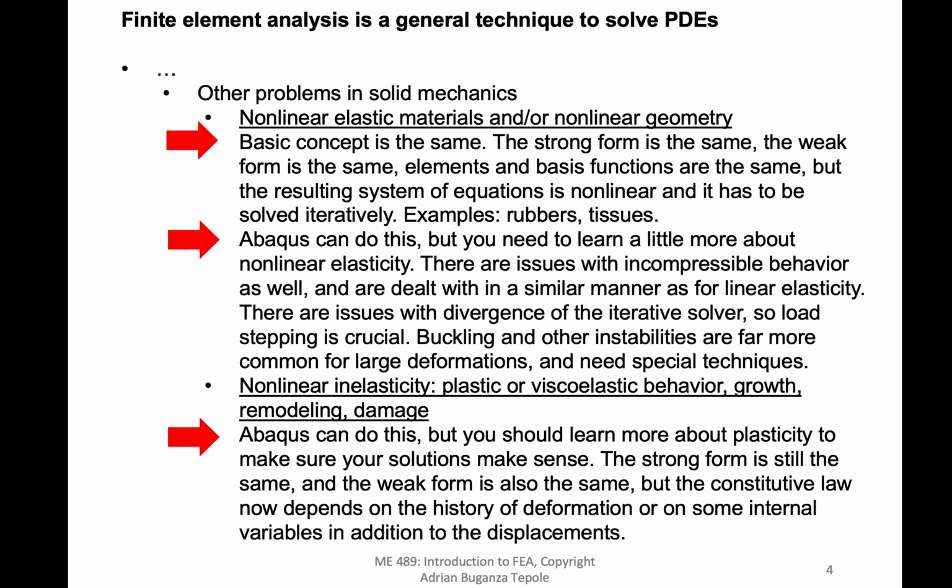It's also used for solving in general some nonlinear equation. So not just for polynomials, but in general to find a solution of a nonlinear system of equations. So this is what Abaqus does. It has an initial guess for the displacements. Based on that, it evaluates how close it is to equilibrium and the derivative of that.